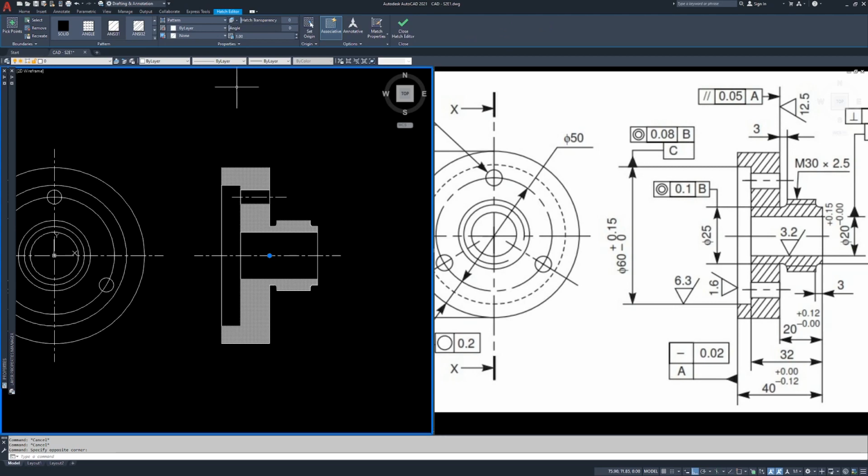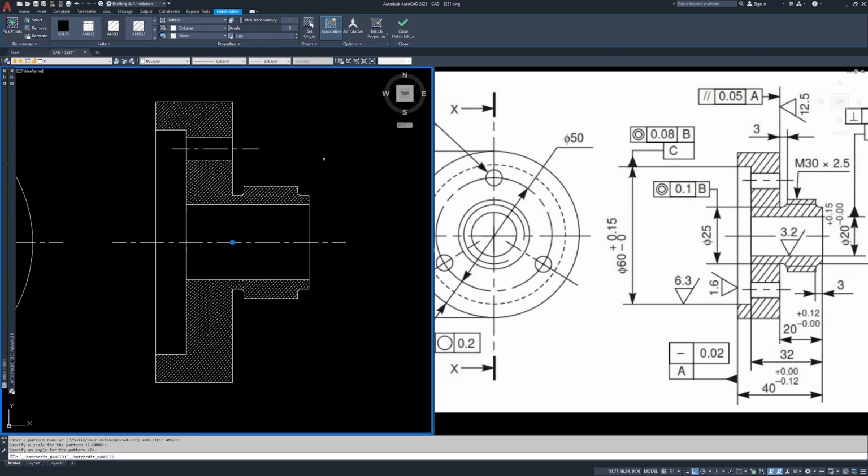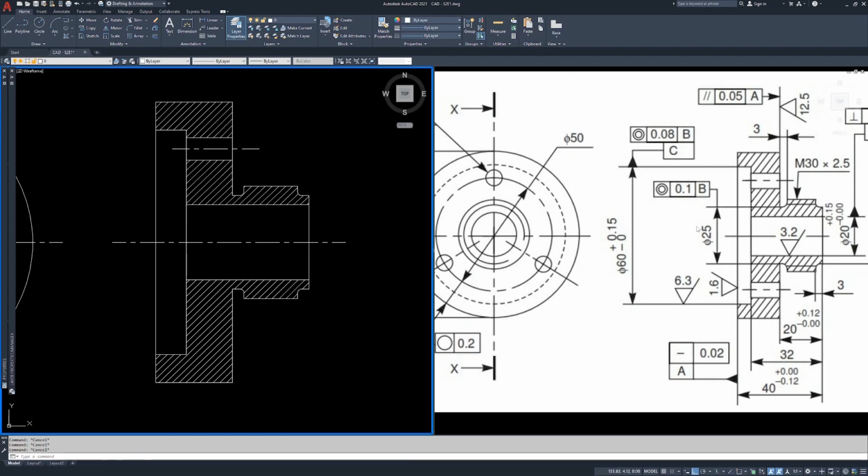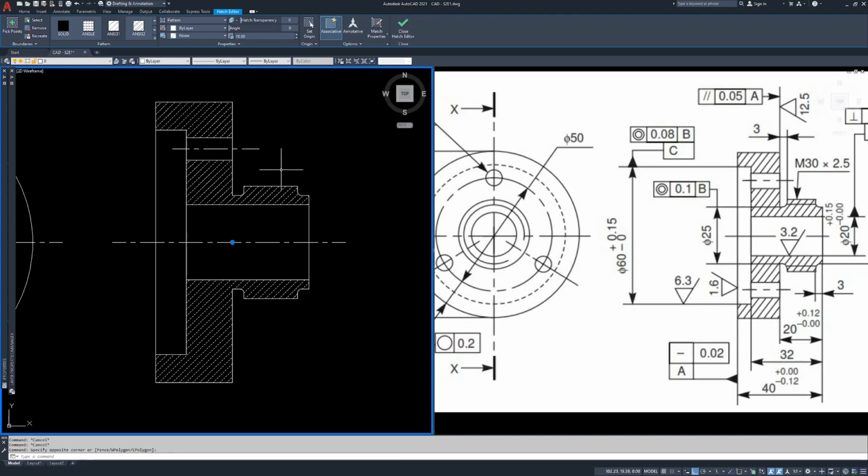I'm going to select the hatches. And what I probably want to do, select ANSI 31 because it's an angled hatch. And then we want to increase the scale. So if you look here in the properties panel of the hatch ribbon, let's crank this up to 5. See how it looks. Zoom in a little bit, hit escape. Nope, 5 isn't good enough. Let's crank it to 10. That's close enough. This looks more like a 30-degree or a 60-degree angle.